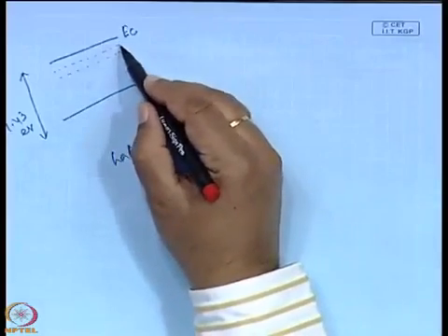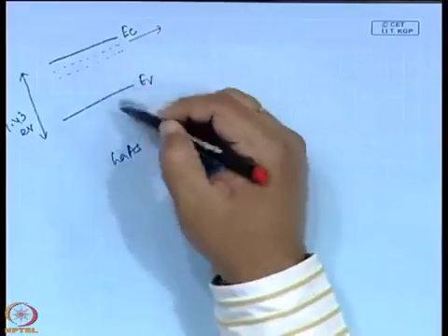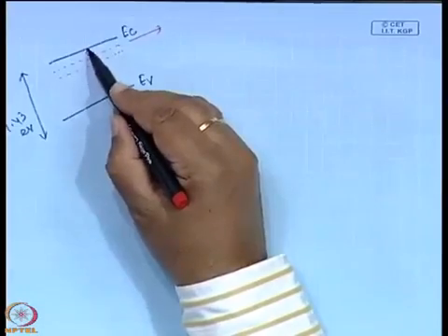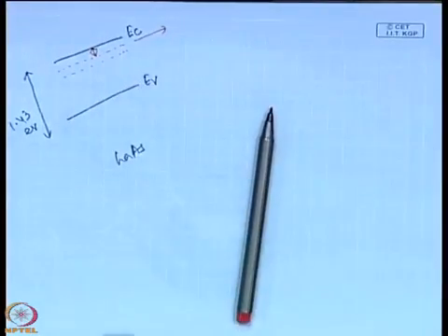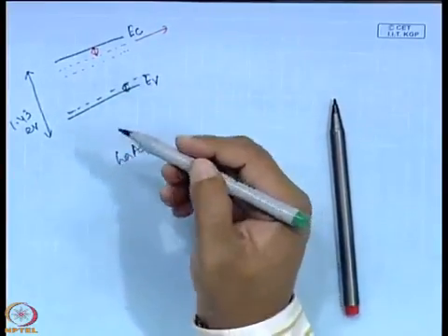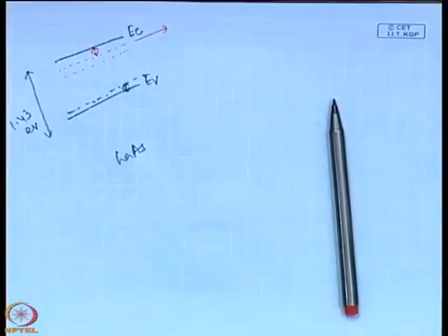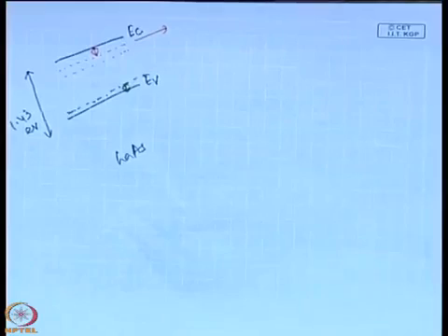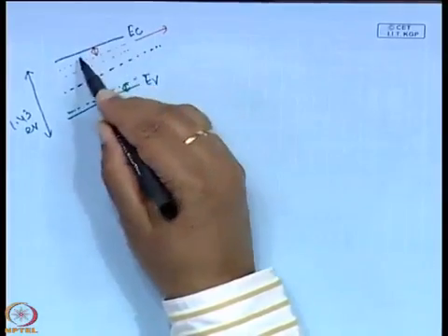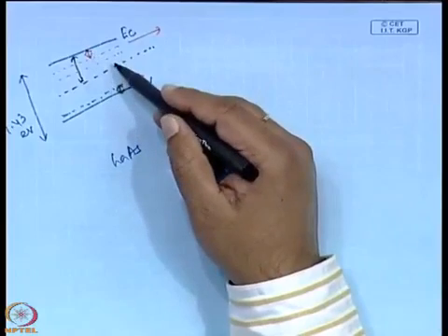If these impurity levels or defect levels, these levels meaning an energy somewhere inside the band gap, are very near to the bottom of the conduction band, or very near to the top of the valence band, say for acceptor states, these are the shallow levels, a few milli electron volt. Otherwise, in some cases you will find that this defect level is actually deep inside the band gap, that means several hundred milli electron volt either from the top of the valence band or from the bottom of the conduction band.